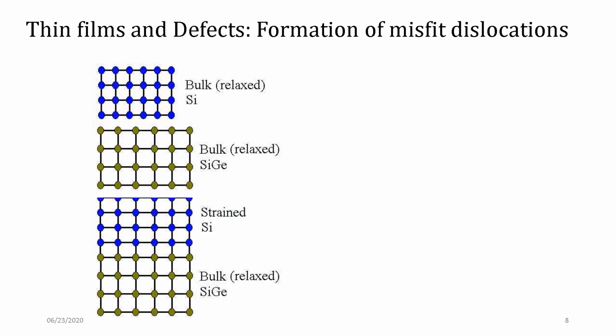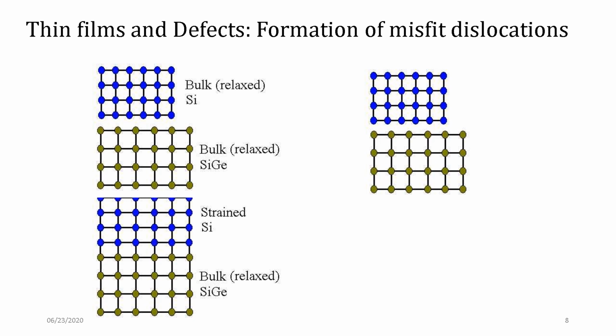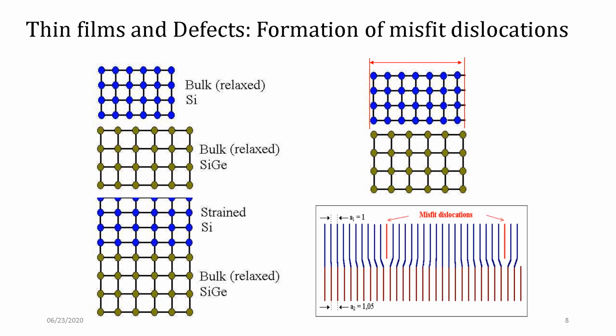And here is just an example of how the crystal structure relaxes when it is strained, and what it is giving rise to when it is stretched. It is stretched this way by the formation of an extra layer, or extra line, of atoms. These are called dislocations, misfit dislocations. This is a defect in a crystal.